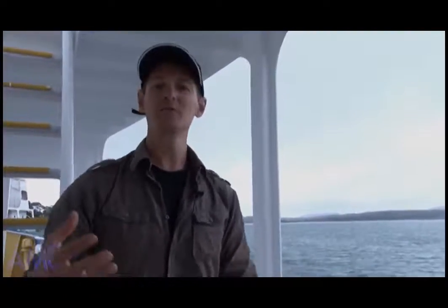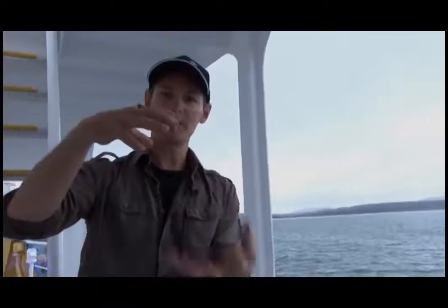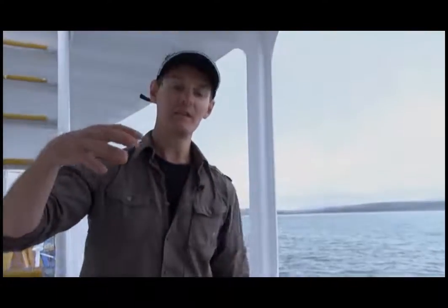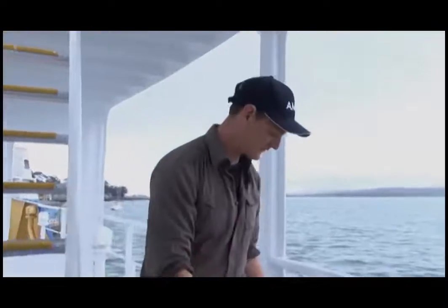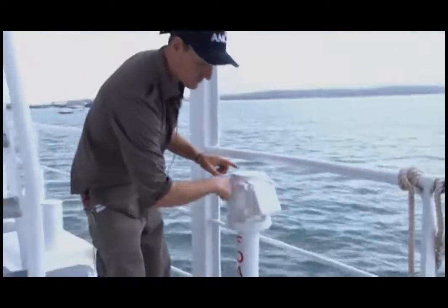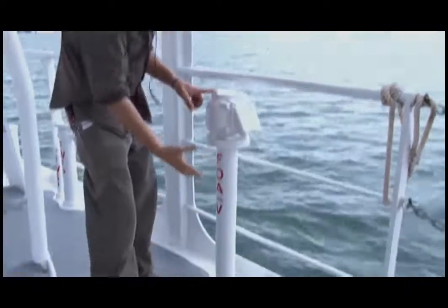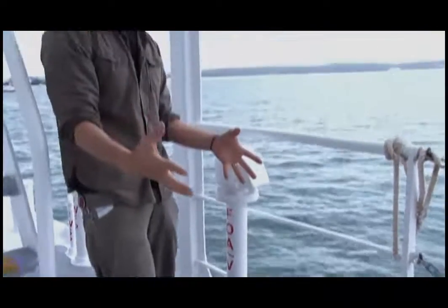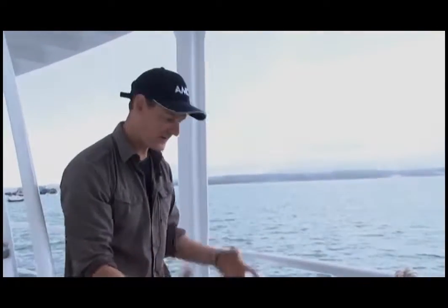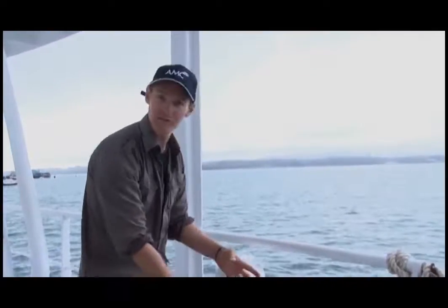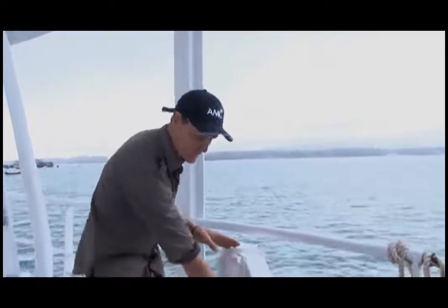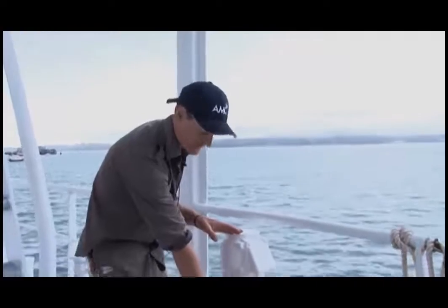So our two main bunker tanks, they have to have our breathers to allow air in when the tank is emptying, and then it needs to dispel air when we're filling. So right now, while we're refueling, air is being pushed out of the tank. Now that serves as a fairly dangerous time in and around this vicinity, because it's pushing fuel vapours out of the breather.